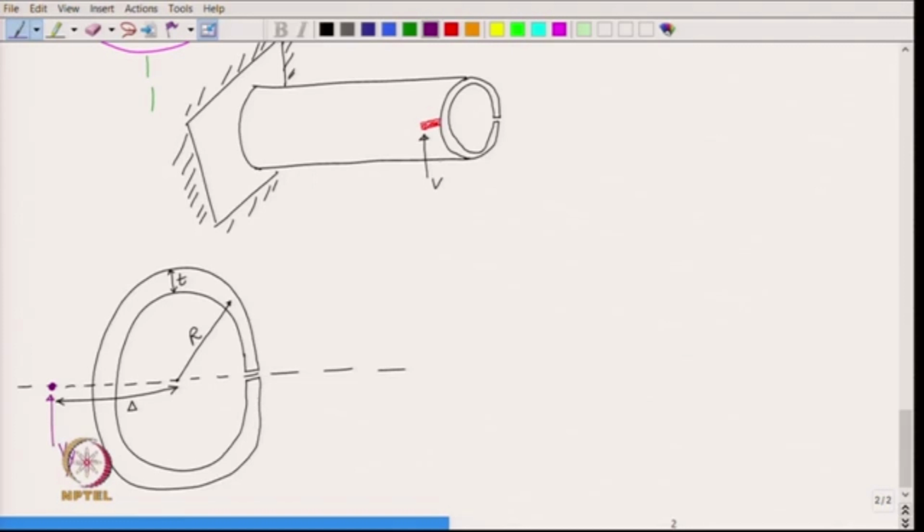Now, we know that the torque due to shear stress distribution has to vanish about the shear center, which let us say is the point A. So, let us try to find out the torque. We have to do an integration over the cross section. Let us suppose we go by arc length s and we look at this segment, and then we have shear stress here,